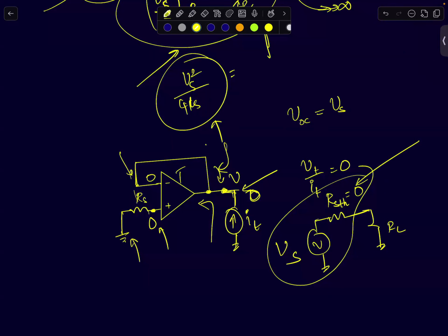It's actually, in effect, transferring the same voltage, but at a much lower source impedance. So it's almost transforming the source for you, so that its power handling capacity is greatly amplified. I'm just saying it simply means that I've just decreased its source resistance. I've just transformed its source resistance. I've maintained the same voltage, but the source resistance is greatly reduced.